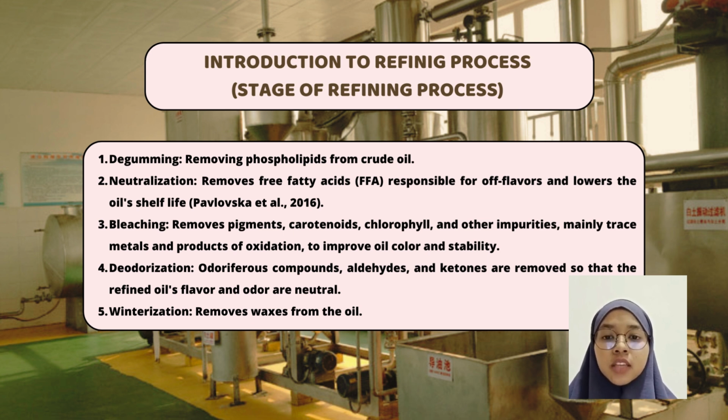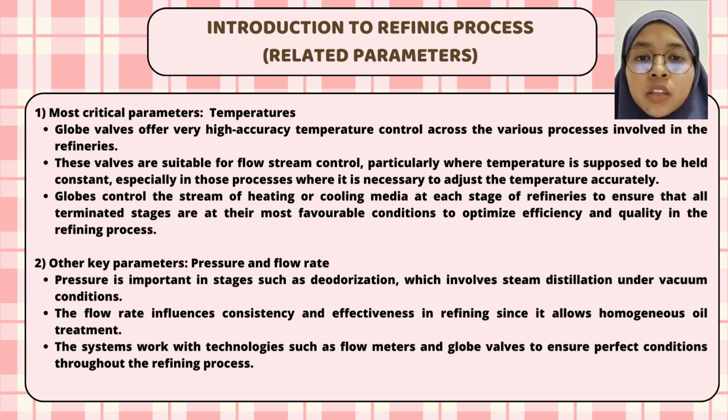And the next stage is deodorization. Deodorization is the process to remove odoriferous compound, aldehyde and ketonoid, so that the refined oil flavor and odor are neutral. The next stage is winterization. Winterization is used to remove wax from the oil. So the next part, I would like to explain the related parameters in cooking oil refining.